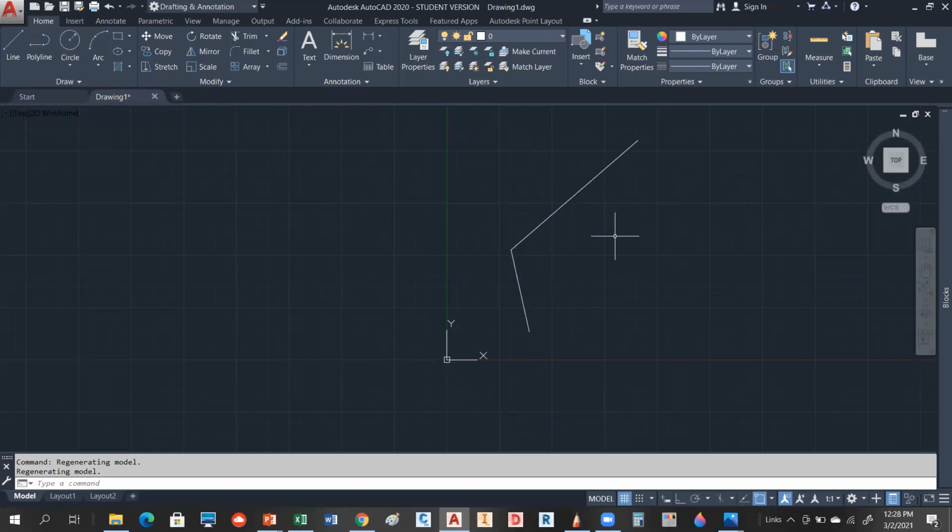All right. Does anybody have any questions on that? You should also plot it to scale, like a 40 scale or a 50 scale. Just make sure that it fits on an 8.5 by 11 size sheet of paper. When you plot, don't plot it scale to fit, okay? I want it plotted to scale. Does everybody know what I'm saying there?